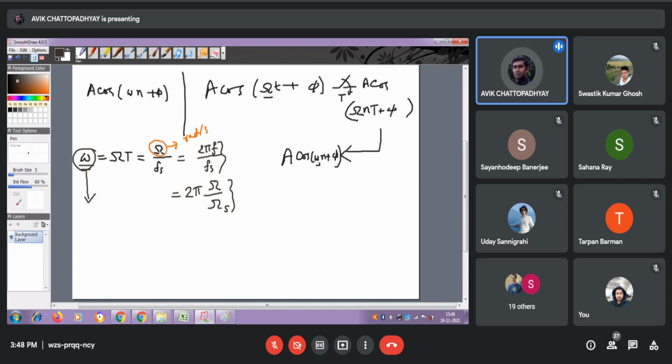And not only that, sometimes people also call it a normalized frequency. It is dimensionless, there's no doubt. So the digital frequency is actually expressed in radians, not radians per second. Radian per second is used to express the analog frequency. A digital frequency, small omega, is, as you understand, dimensionless. So only to indicate that it is an angle, people associate the radian term with it.